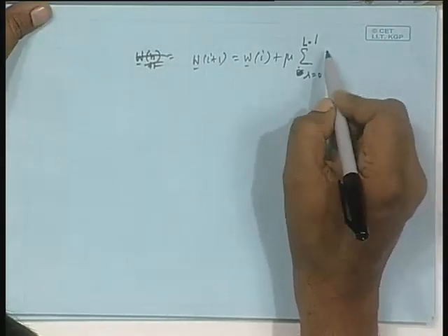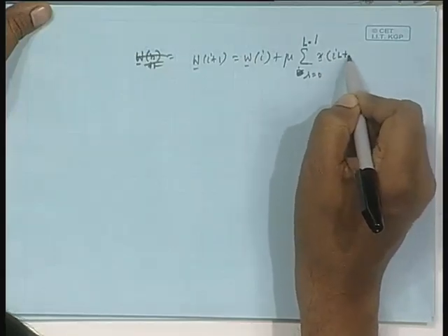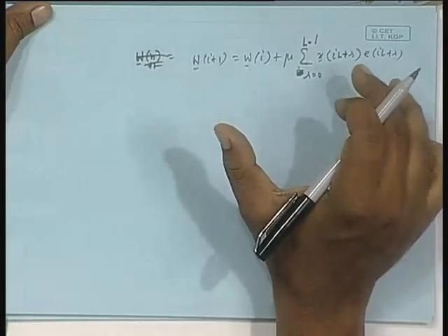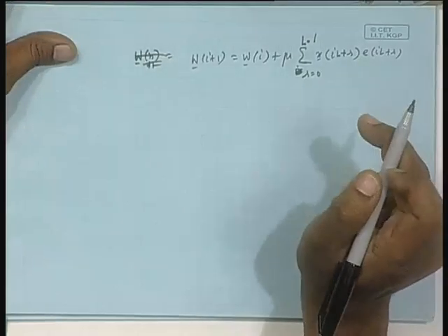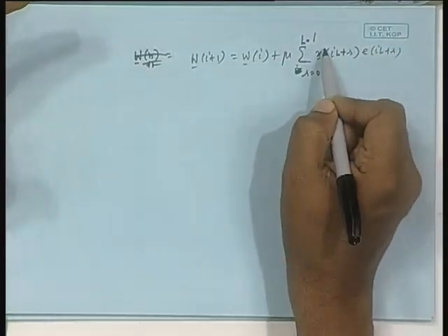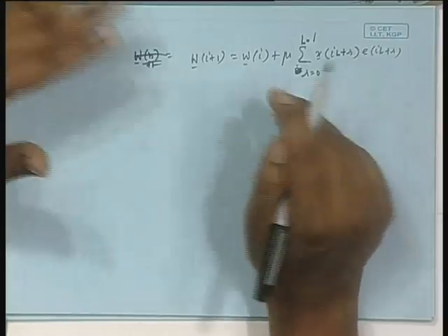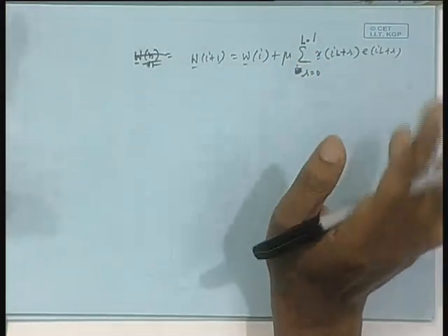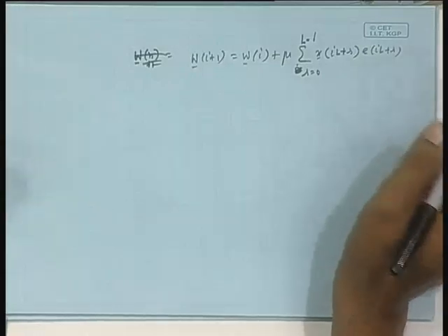Okay. And we have got these things, the x vector. By the way, if it were a complex LMS algorithm, the whole derivation would be the same, but there will be a star here, isn't it, x star, or star on e. We will be considering that extension, because when I do this FFT business, I will take care of that also when it is complex. For the time being, we are assuming real.